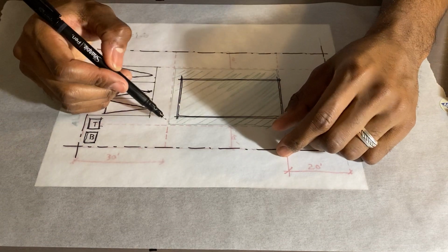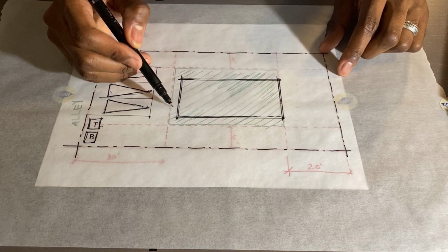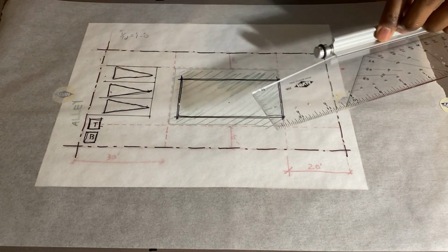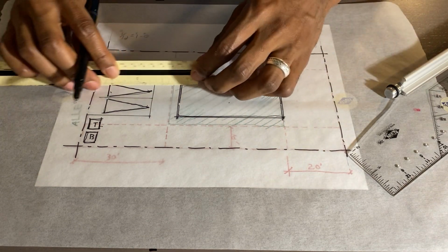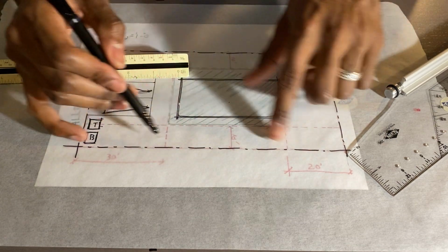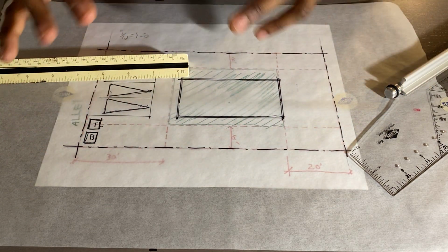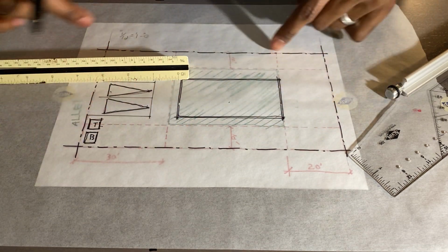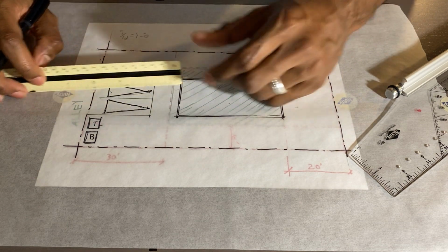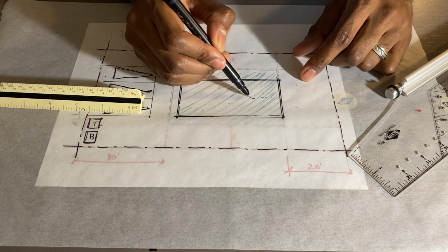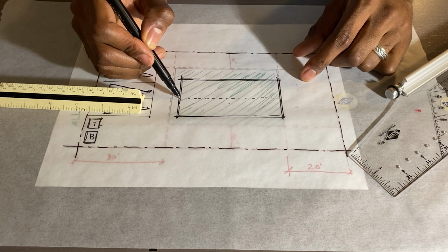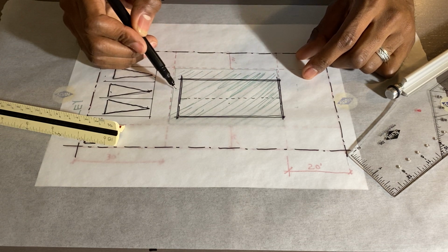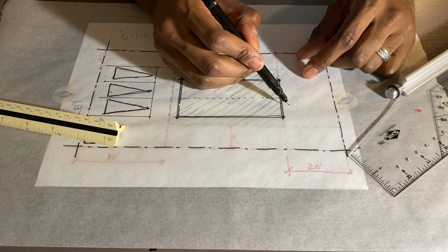And then we'll do, that's recycling or reusables, things like that. And then what you want to do now is sort of establish how one gets from the building to this area. And this is where you can kind of freehand it. You're allowed to use all this area for surface stuff, for paths and things like that, permeable area, grass area. As long as there's no building on these setback areas, you're good, right? So, I've got 2 units here. Let's just say this is my party line between those 2 units, shotgun units. We've got an entrance up here. We've got a rear exit here, rear exit for that one, front entrance for that one as well.